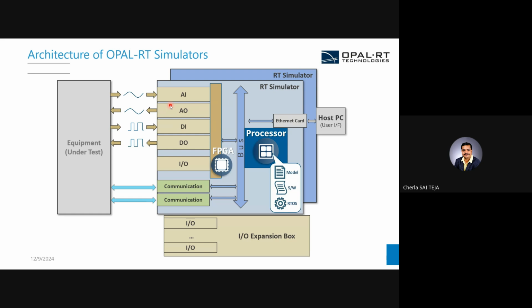And it's the same for any application actually. The device under test can be anything. The required appropriate plant should be running here, and by using the IO channels, today I can use it for an FOC control of a PMSM motor. Tomorrow we can use it for DTC control of an induction motor. So we can use the same simulator for a number of projects. That is one of the better places for real-time simulations. It will help you to test and validate different control algorithms in a much faster way.